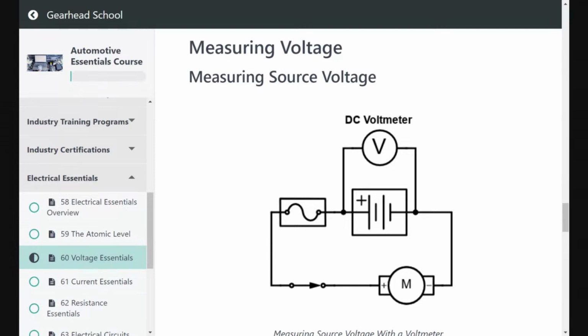And that's why it's called source voltage, because that's the source of the voltage to run the car on. That's the fundamental, kind of the first voltage check you probably will use on a normal basis. Car comes in, you will see, is it charging? Is the battery charged, steady charge? All will go back to source voltage.